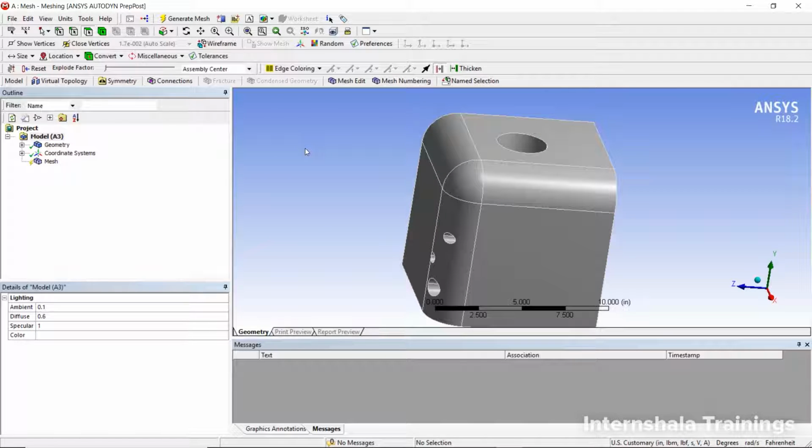So as I told you, we have an automatic mesher that is inbuilt into Ansys Mechanical, which is very efficient in generating initial meshes. For example, if the body is very simple, the automatic mesher is going to very accurately generate the mesh. But if the complexity of this geometry increases, this mesher can be used to create an initial mesh, and from that initial mesh we are going to use some localized controls to generate a more efficient mesh.